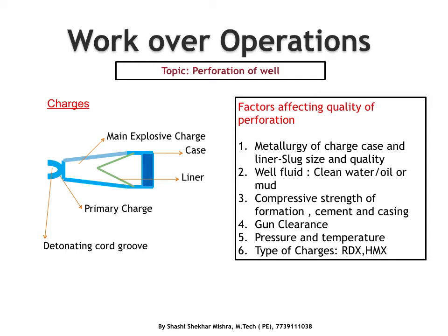Another factor depends on whether we are doing the perforation overbalance or underbalance. In underbalance, if we perforate, the well starts to flow immediately, which is quite effective in dislodging the debris of the charges, the loose crust, formation bands and all this, and so it gives better flow performance than an overbalance formation.